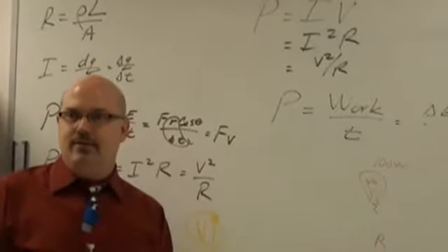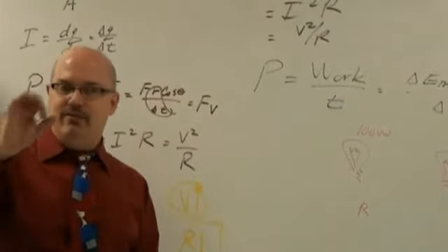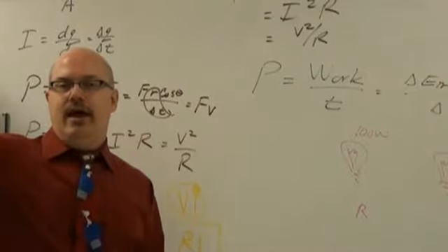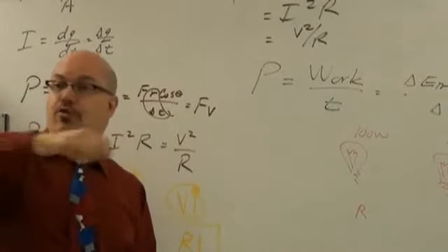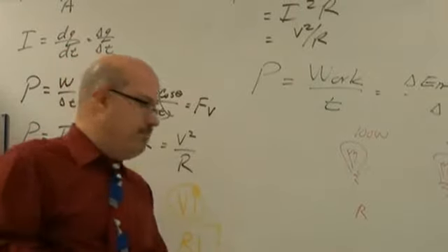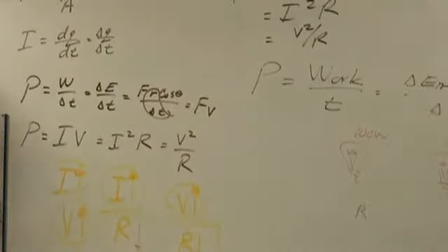Okay? If you want your oven to generate even more heat, then you'd make the filament even fatter still. Okay? So you'd have less resistance and more energy would flow through it for any given amount of time and it would generate more heat. Okay? All right. So there you go. There's power. We have those three equations for power and we use whichever one seems to be appropriate to us.